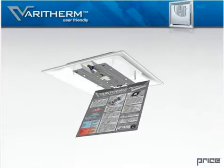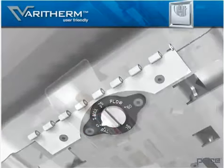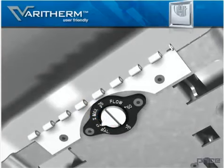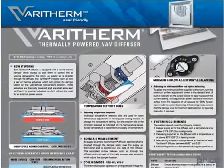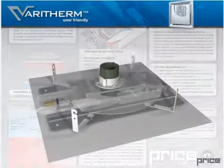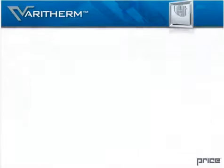Simply opening the plaque allows the user to make control adjustments. The plaque pivots securely on a solid hinge and is held closed by a set of powerful magnets. Easy-to-read gauges let you know what your settings are. Temperature is adjusted with the spin of a dial, and the minimum airflow setting is adjusted with the turn of a screw. The unit is also equipped with a forced open mode to assist in system balancing. All guidelines are simple and easy to follow and are written in a clear format on each unit. Optimal security fasteners mechanically lock the core into the back pan, where required by code.